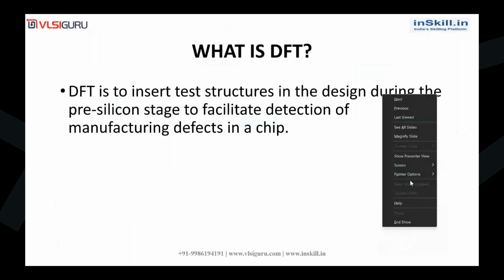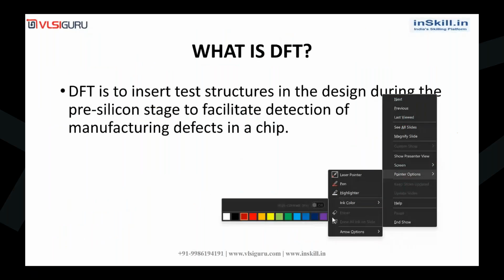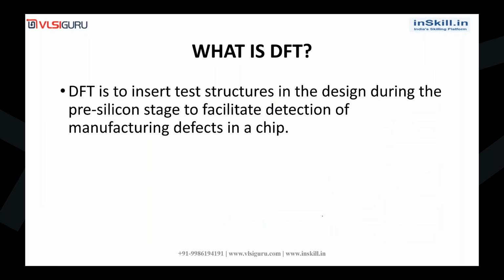So what is DFT? DFT is actually to insert test structures into the design. We will be adding our own test structures into the design, like scan insertion, MBIST insertion, boundary scan insertion, during the pre-silicon stage. Pre-silicon stage means before manufacturing.